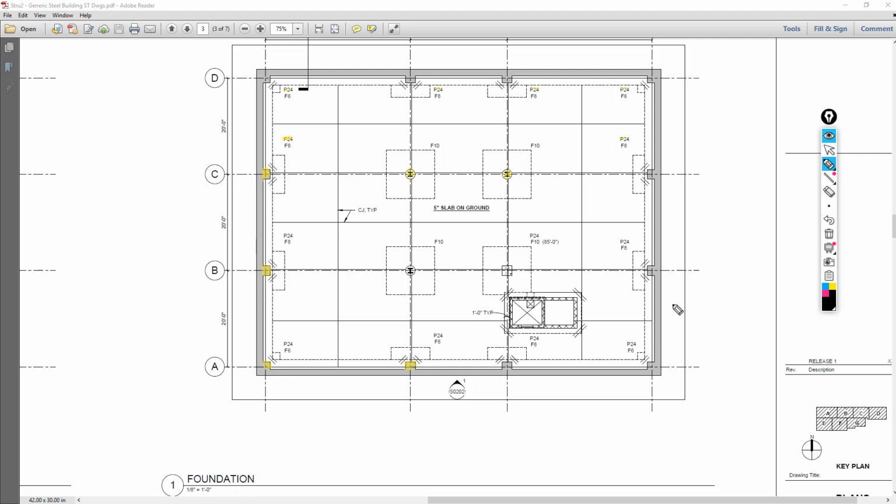Around the perimeter we have this big, thick concrete retaining wall, and so we aren't able to bring the steel all the way down. So instead we create this little pier pedestal for it to sit on. And these steel columns would terminate at the level above.